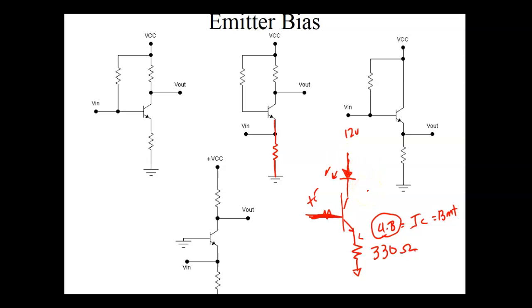Well, what would... so this could be germanium. It would do 4.3 milliamps and it would drop... For one thing, LEDs are not made out of germanium, and they're not made out of silicon because they don't produce enough photons. LEDs are made out of gallium, and then they're doped depending on what type of color you want. So if we don't look up the LED, or if I don't buy it, we assume it's approximately 2 volts. Period.